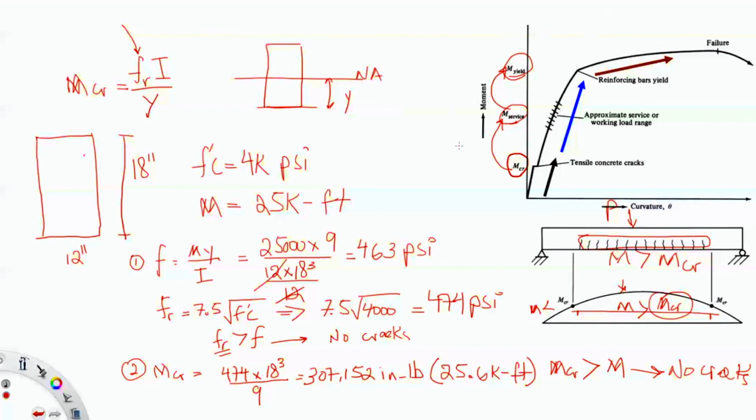Actually, I forgot to mention that concrete, generally, even if it didn't crack, is so weak in tension that in design we consider it as 0. We are depending 100% on the steel to take the tension, not the concrete.